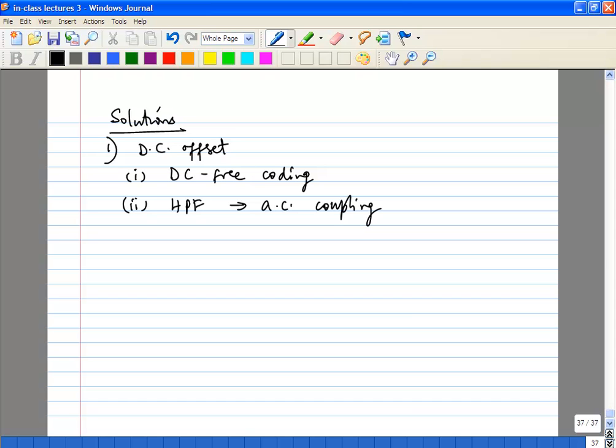Now obviously, the lower you want to cut off, which means you can transmit more information in the signal itself, the lower you go, the larger the capacitor. With the larger capacitor, you have settling time problems, so that's a big deal. You need to go really, really low if you want to use the low frequency content in the signal, so your capacitors will become huge. That is another problem. Settling time problem will only come if you talk about a large signal, like a large signal at the oscillator.